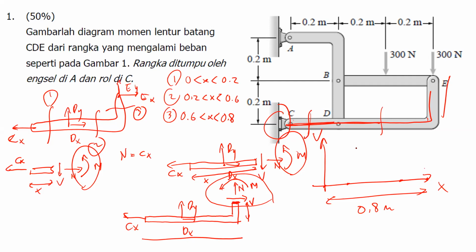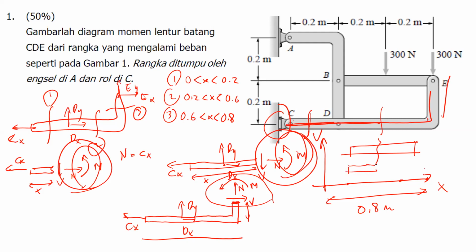I thought that you were drawing the right side of the cut across. No. This one is the right side of the cut. This one is the right side of the cut as well, right? So whenever we have something like this, then we cut it here. If we analyze the left part, this part, the moment positive is supposed to be like this, clockwise. Correct or not?